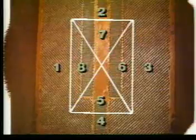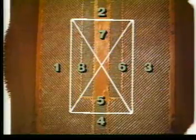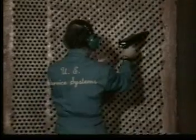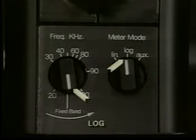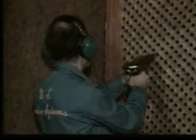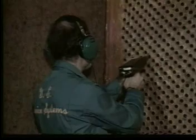If a quick scan is inconclusive, divide the condenser tubes into testing zones. Start scanning peripheral tube zones where sounds are loudest. Set the Ultraprobe to log and use it in the fixed band position. With the rubber probe, scan a sample tube and adjust the sensitivity to read 50 on the meter. Scan for the loudest deflection in the test zone.